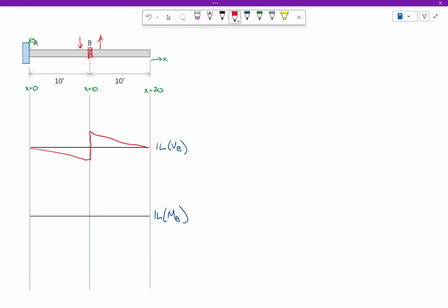First off, what's happening here? This point is rotating, right? But I installed a shear release. I didn't change anything here. This point cannot translate or rotate. It's got to stay flat. If it doesn't stay flat, it's bending. What did I tell you? Influence lines are lines. They're straight. There is no curved segment in a determinate influence line. So this can't deform. It's got to be straight.